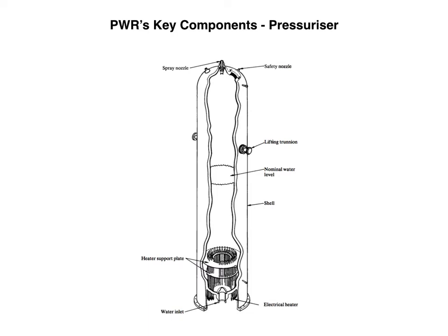When the electrical load is increased instead, the decrease in coolant volume drops the water level and reduces the pressure in the pressurizer. This causes some of the water to flash to steam, limiting the pressure change. At this time, the drop in the pressure actuates the heater to further limit the pressure reduction.